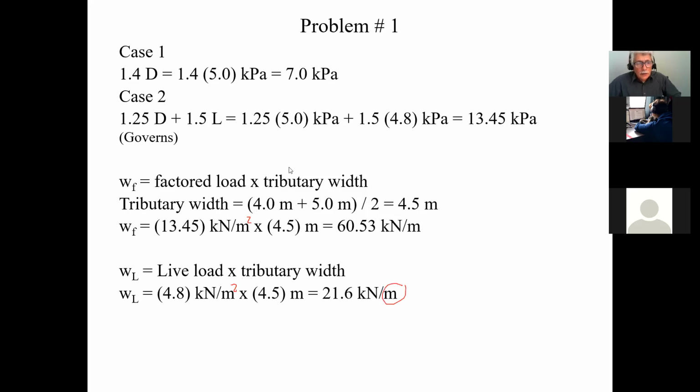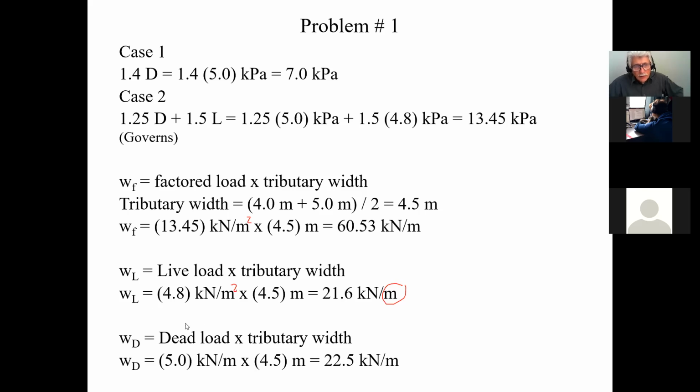So now, of course, I also want to calculate WD because I will need this to calculate my deflection under dead load. And like I said, when you're calculating these service requirements, you always use the specified loads. In other words, you do not factor the loads. You always use the specified loads, and you don't factor the loads, okay? If you happen to use the factored loads, well, it's only going to be that much stiffer than what you actually need, but you don't.